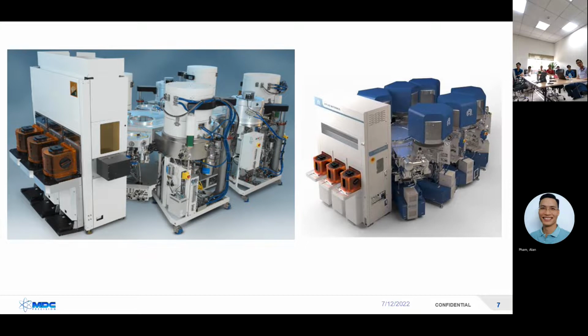A new wafer goes in, and they do that over and over and over for about 50 wafers at a time. So like, if you remember that first one where we etched the holes, okay? So that would happen to all these wafers. Then they would go to another machine that would clean off that mask. Then they would come out and they would go to another machine that would do all the super clean, it's kind of a wet machine. Then they come back out and then they go to the one that puts down that orange layer, okay? They all kind of look like these machines, but the process chamber here does something different, okay? Understand? A little bit? Yes. Okay.